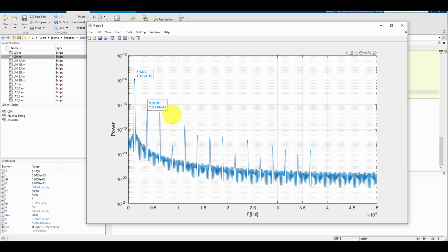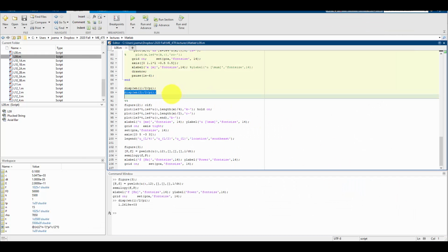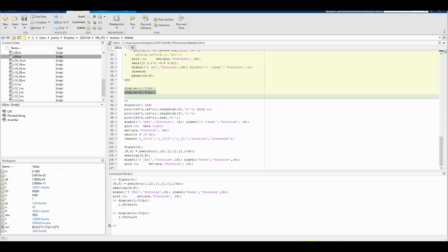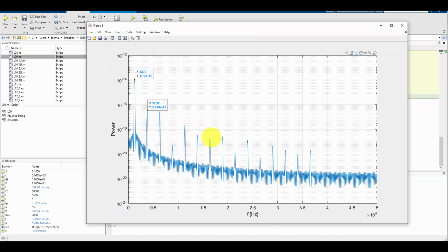All right, so the peaks on these, I'll check the second peak as well. I have this 3809 Hertz coming out of the pwelch. Again, it matches pretty closely to what we get from the analytic solution, the 3786. And again, sampling it longer, I would probably get even closer to that value as my resolution is going to increase. So we see a bunch of peaks here. We have 1, 2, 3, 4, 5, 6, 7, 8, 9, 10, 11, 12, 13, 14, 15 peaks, and then the peaks stop here. So we would want to know, why did the peaks suddenly stop after 15 of them if we're going to have an infinite number of natural frequencies in continuous systems?